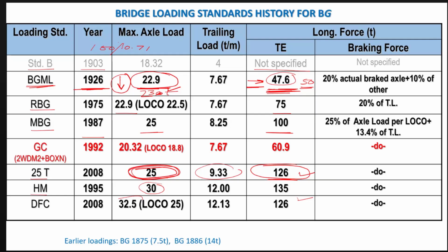That way we can plan so that the load will not transfer there, or make a construction joint if we are making it monolithic. Or by making it at top level we can increase the foundation, make a separate one for that, and for the pier cap level we can expand it. Like that we can make our design considerably if we don't have the drawing of the existing structure. That way we can go ahead.